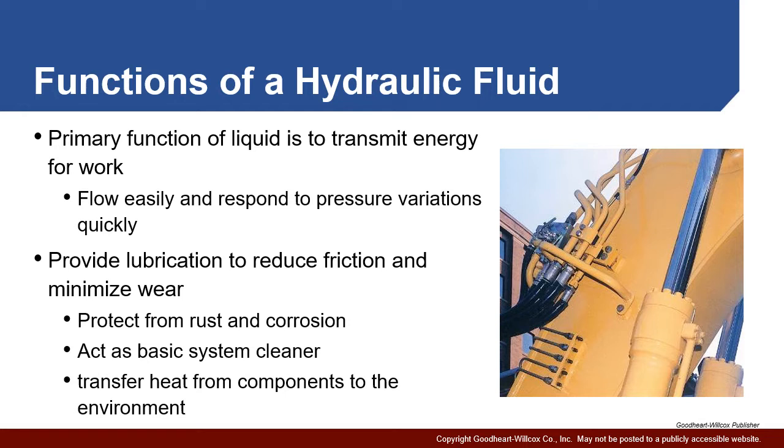So what other kind of things would we like our fluid to do for us? Well, one of the main benefits, particularly of hydraulic oils, is that they provide lubrication. All of our components are essentially bathed in this fluid, so it actually provides the seals and the lubrication for the devices. So we reduce friction, and as a result, the components have longer life in that they wear less. In addition, we want to prevent our components from rusting. Most hydraulic components are steel, and steel does rust. So hydraulic fluid will hopefully help to prevent that.